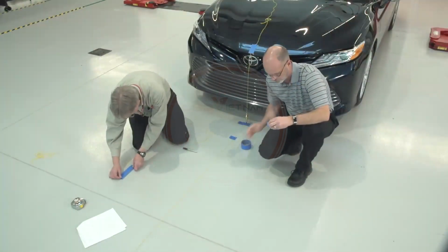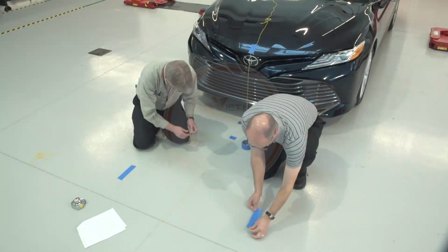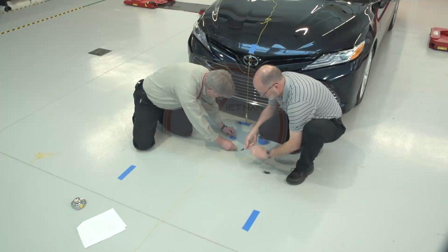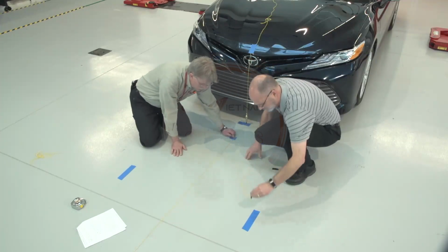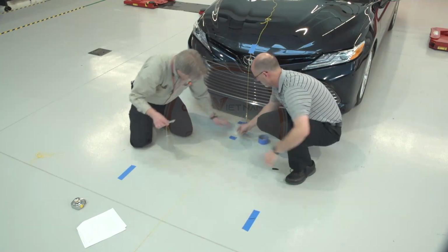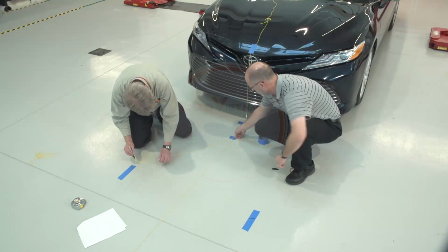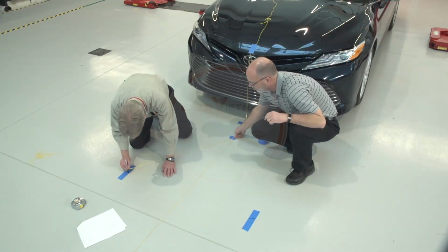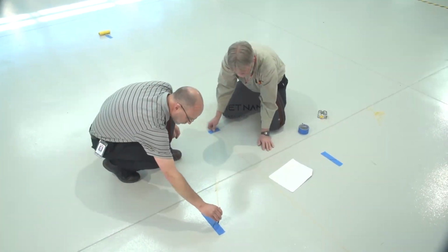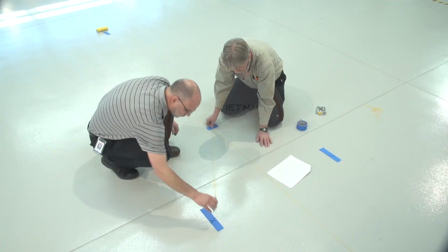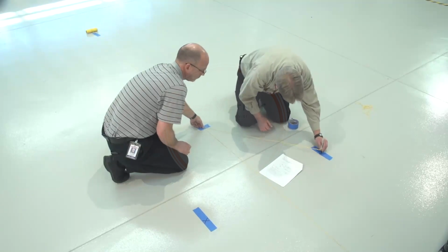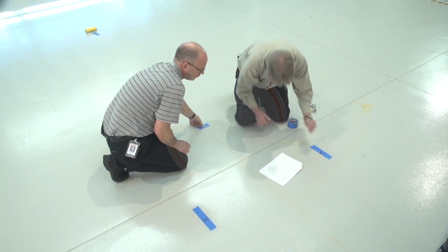The next step is to create a line that crosses the center line halfway between points C and D. Use a 1,000 millimeter long string attached to a marker. Start at point C and draw an arc to make line E. Then repeat this process to draw an arc on the opposite side of the center line to make line H. Now, move to point D with your 1,000 millimeter line and marker and draw an arc creating line F. Again, repeat this process on the opposite side of the center line, drawing an arc to make line I.